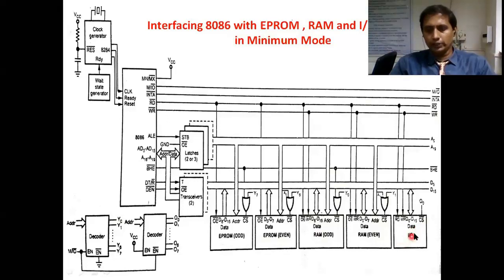Similarly, for selecting IO, IO also has read and write. IO is suitable to perform 16-bit data transfer at a time, that's why D0 to D15. Remember, all data lines are bidirectional, see the arrows. Whereas address lines are all unidirectional. Here also there is a chip selecting signal. The IO chip selecting signal is activated from the decoder output.